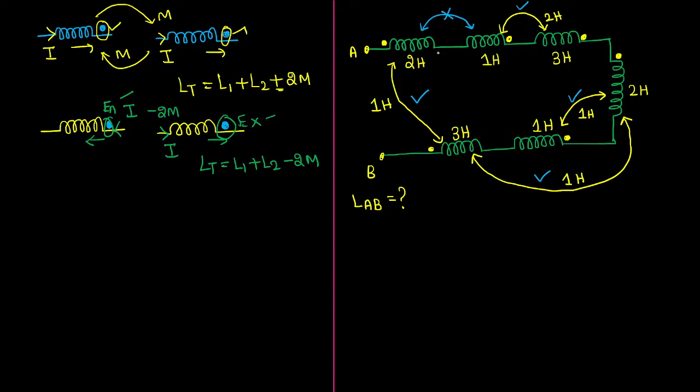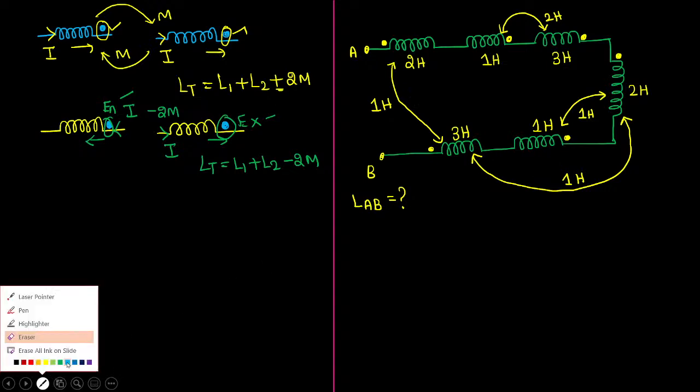They haven't given. So if they have not given this kind of lines, you have to understand that the mutual inductance between those coils is 0. That is the meaning of that. So you have to consider the mutual inductance only for those which are highlighted by them. You don't need to be bothered in this kind of circuit. Mutual inductance will be clearly given by them. They will give you everything. You don't need to be bothered about it. Okay, so you can consider only the given values.